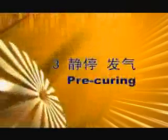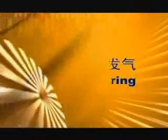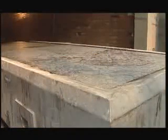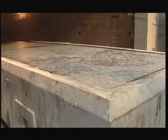3. Pre-curing. The poured slurry is ferried to the pre-curing area by ferry carts and transferred to the designated rails there by the hauling machines of molds for pre-curing. The slurry expands and stiffens into a cake after 2 to 3 hours of constant temperature curing.